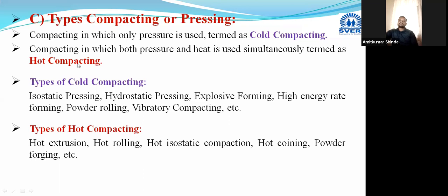And if during the compacting we have used pressure with the help of the upper punch, lower punch, or both punches, and simultaneously we have provided some amount of heat also, then that type of compacting is termed as hot compacting.